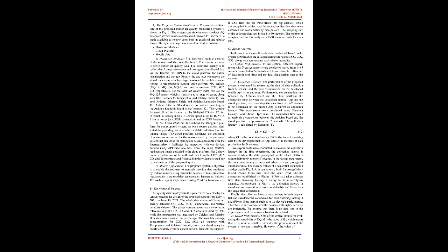Ht represents a state transition matrix to model xt-1, and Bt represents the control matrix to model ut. Wt denotes the process noise at time t, representing the effects of influential external factors on the system. In the proposed model, the statistical characteristics of Wt are assumed to be normally distributed with a mean of 0 and a covariance matrix Qt, so that the sensor measured value Zt relative to the real state at time t is mathematically represented by equation 3.